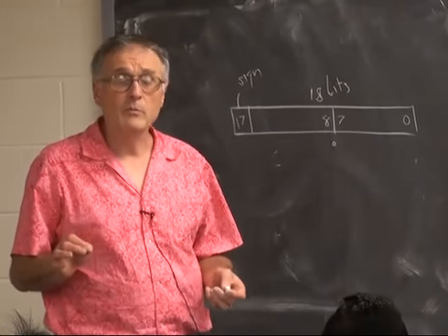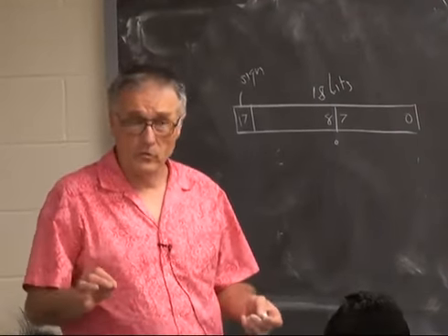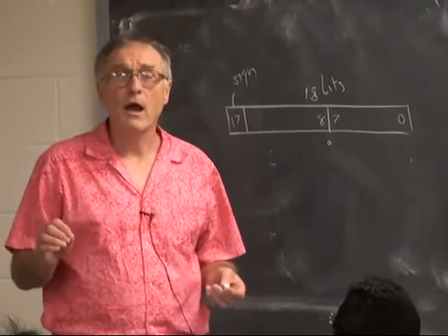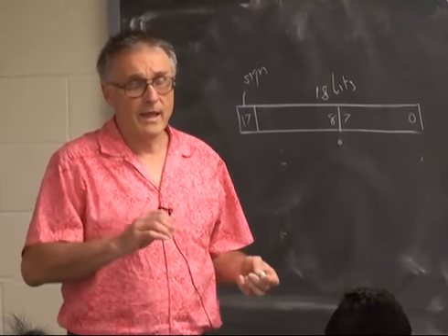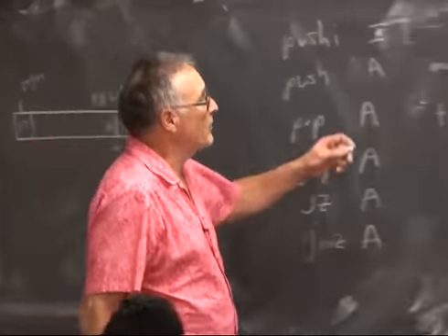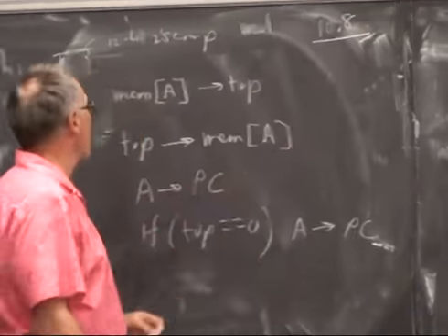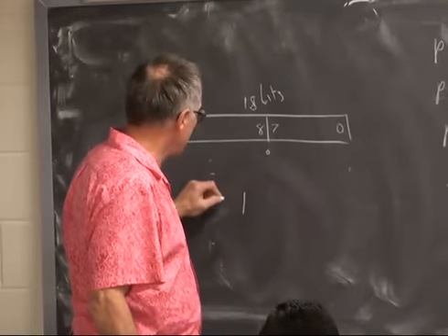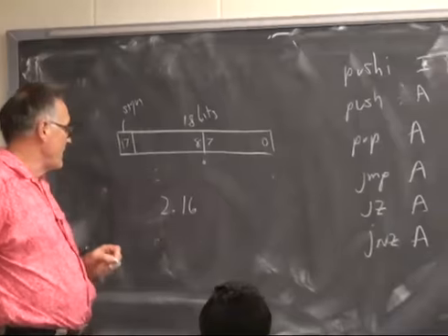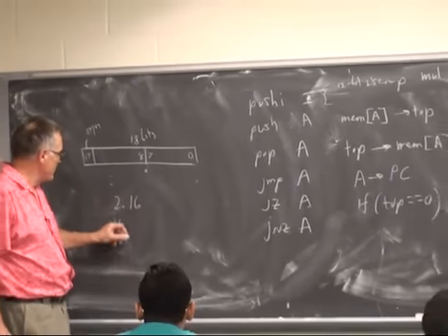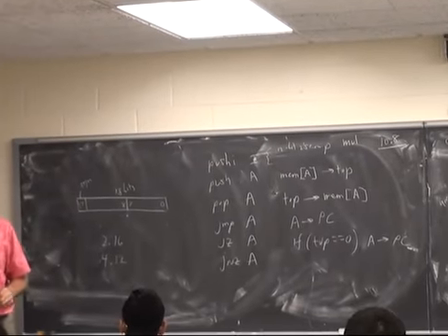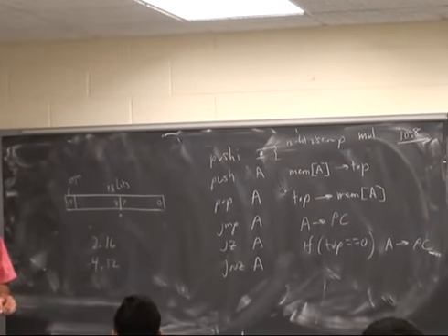In fact, probably what you're going to have to do with this processor, the single change you're going to have to make to the processor, probably to make this lab work for you is to change this multiply from 10.8 format to 2.16 format, or maybe 4.12 format, so that you have more bits of fraction and less of integer.